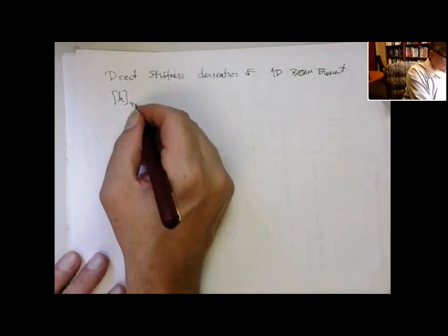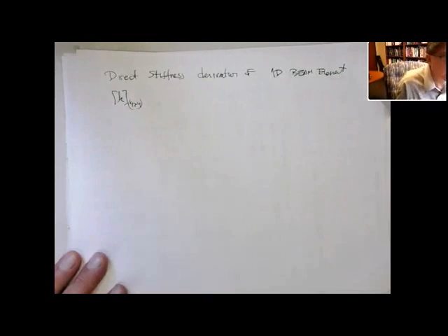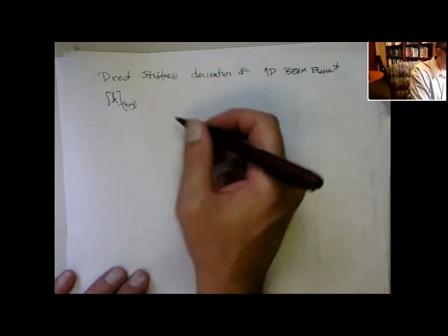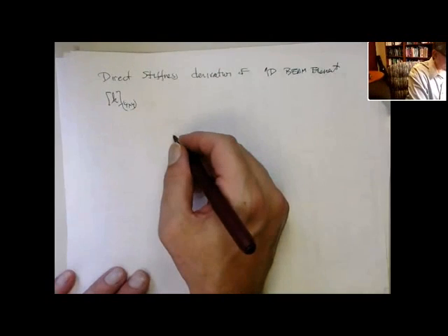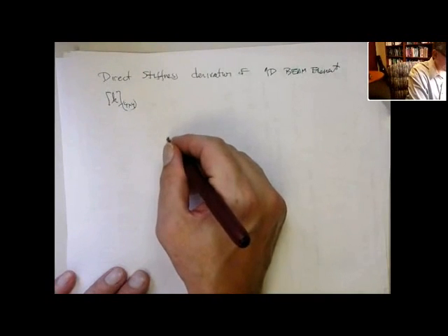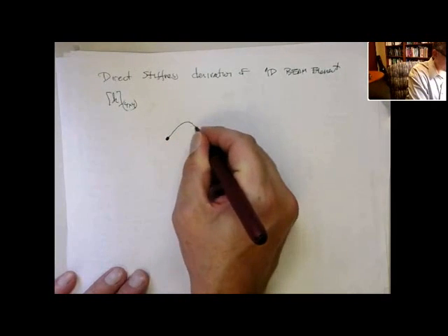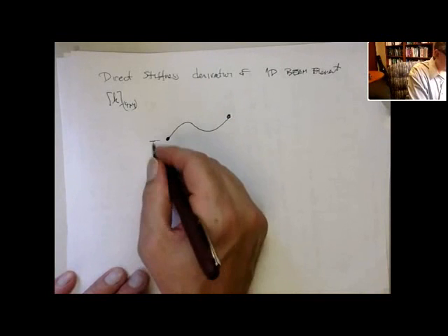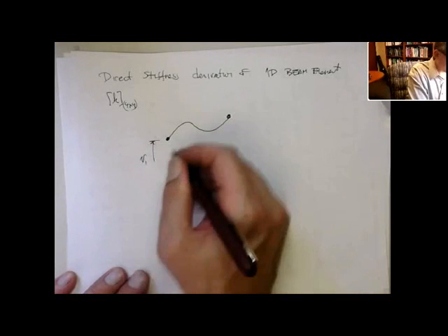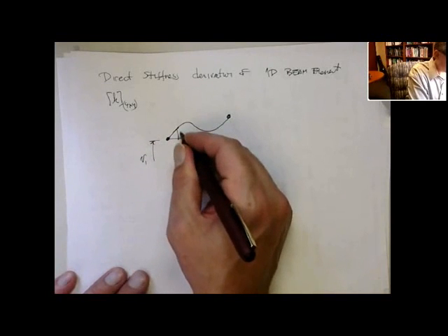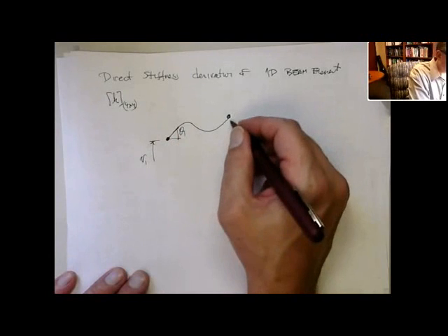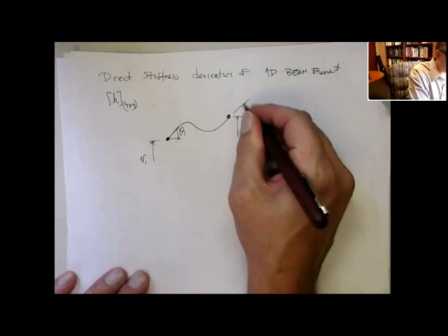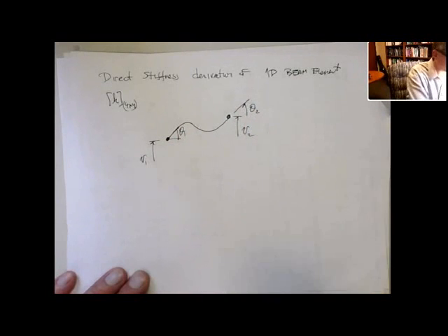This is the 4x4 one, right? All right, this is what we started. Well, actually, I didn't start a class. I just kind of presented it. But here we're talking about a beam element that can deflect as follows. It has 2 degrees of freedom per node, a V1 and a theta 1, and then a lateral displacement at node 2, and then also a rotation at node 2.